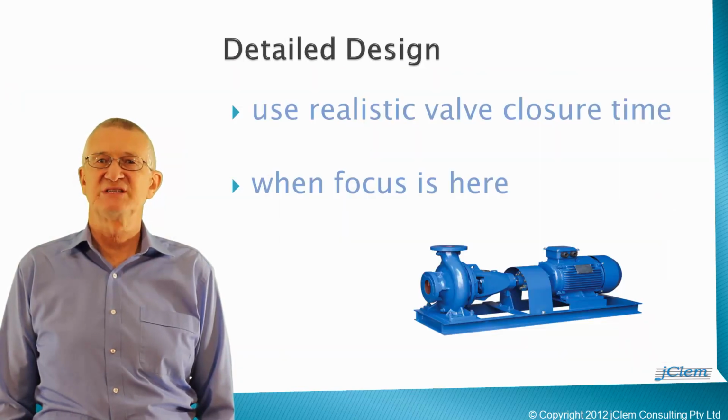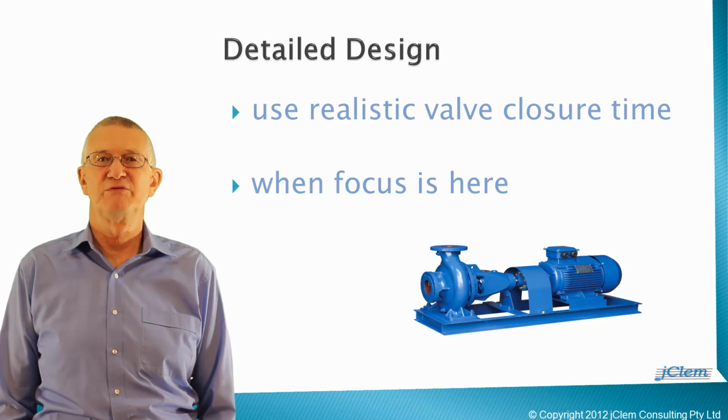At a later stage of each pumping project, when the design team is selecting the mechanical equipment within a pump station, it becomes appropriate to do a series of transient simulations using realistic non-return valve closure times. At that stage of the project, transient simulations should be set up to examine the magnitude of reverse velocity the system can generate and the consequences of the non-return valves slamming shut.